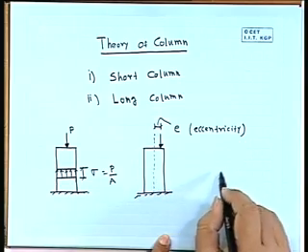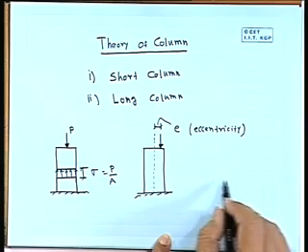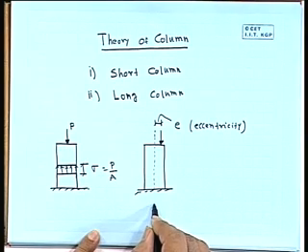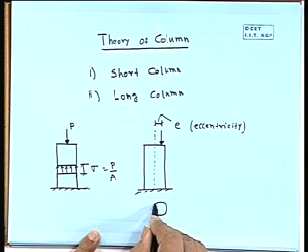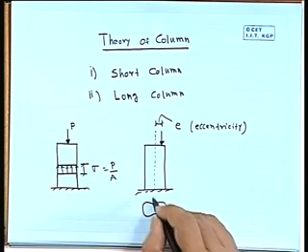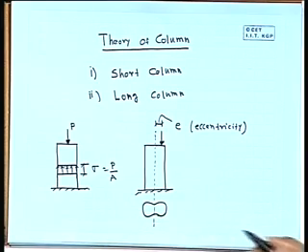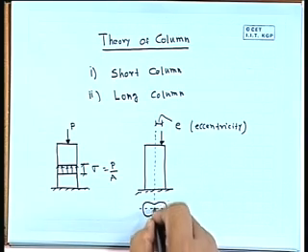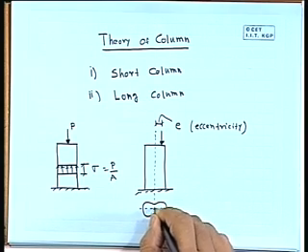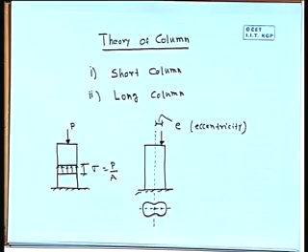Now, the cross section may be a rectangular cross section, it may be a circular cross section, it may be some elliptical cross section or any arbitrary cross section. Say if we take a section, what will be happening? Say if I draw the section here, there might be a section like this also. So, just arbitrarily I have drawn. Main idea is this part should be symmetrical about this. Now, so this will be the centroid and the load may be acting not at that point, it is acting at some other point. So, the distance between these two we say it is the eccentricity, right.